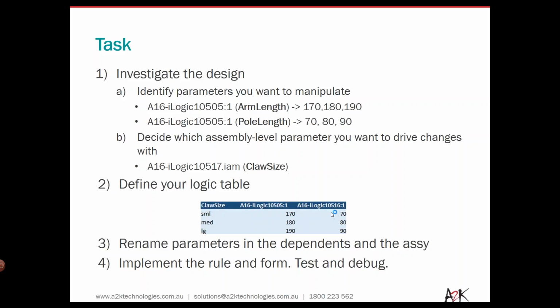Some of you may have heard of tautology tables. This is a programming step that allows you to cover every exhaustive possibility so that you can cover all scenarios. That makes your code robust, and if you do have any situations which are not covered, that are out of bounds, then you can have your iLogic provide a message box.